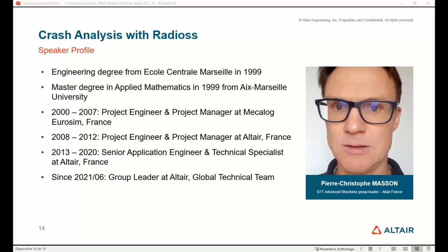Warnings really depend, and one needs to look at the warnings in the starter file, as I did in the presentation. We need to check if these warnings are relevant or if they are already managed by some option in the solver, such as the management of the initial penetration in the contacts. That is possible. Yeah, those are mainly the different messages we can have either from HyperWorks or from Radioss at starter.